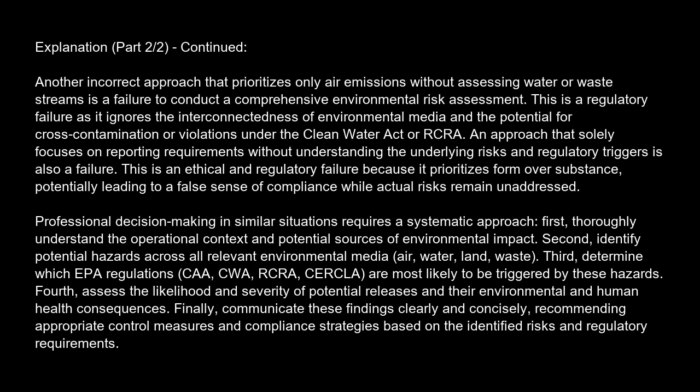Professional decision-making in similar situations requires a systematic approach. First, thoroughly understand the operational context and potential sources of environmental impact. Second, identify potential hazards across all relevant environmental media: air, water, land, waste. Third, determine which EPA regulations, CAA, CWA, RCRA, CERCLA, are most likely to be triggered by these hazards. Fourth, assess the likelihood and severity of potential releases and their environmental and human health consequences. Finally, communicate these findings clearly and concisely, recommending appropriate control measures and compliance strategies based on the identified risks and